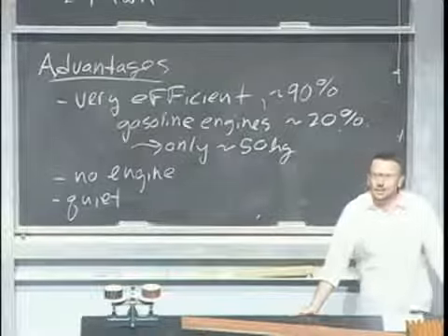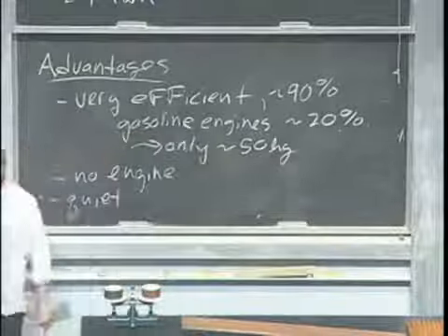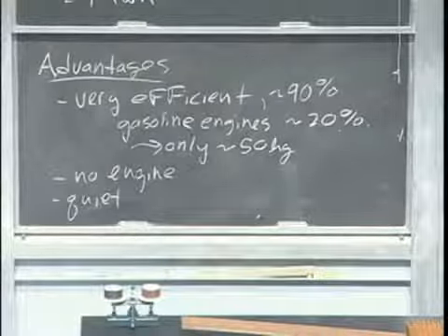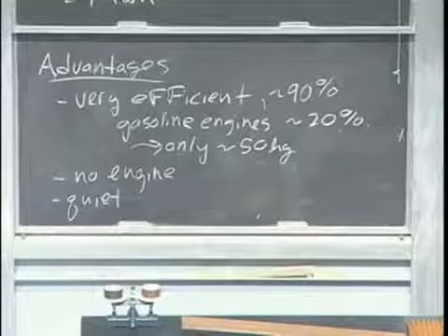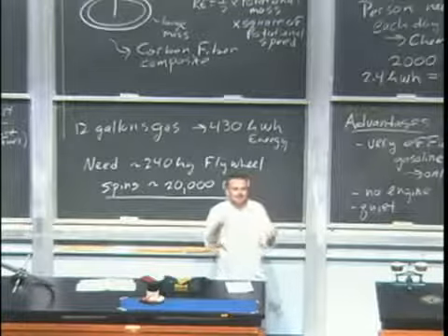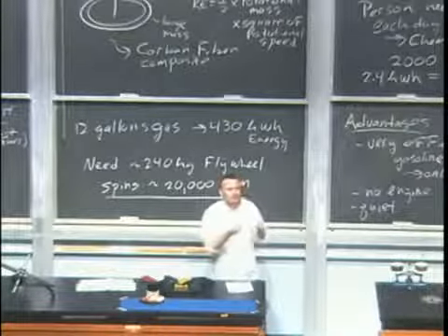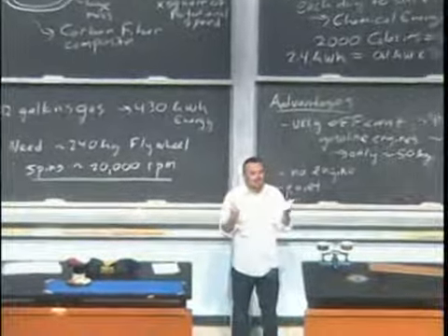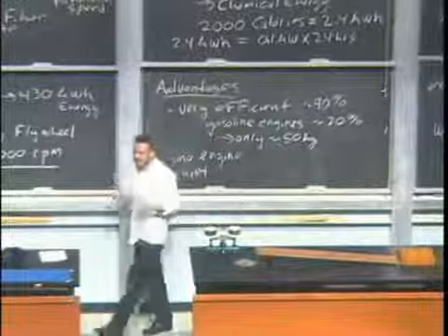Okay. The carbon fiber flywheels actually get around that problem quite a bit because they naturally break up into tiny little fibers. So instead of breaking up into big massive chunks that would go flying elsewhere, and by the way, this might also happen if you get in an accident, right? Suddenly your flywheel gets hit and breaks. In this case, the composite materials like the carbon fiber will break into little tiny shreds. You've got little tiny pieces flying out. They're actually really easy to stop. So your flywheel will just be encased in a little bit of shielding and be able to stop it, no problem.